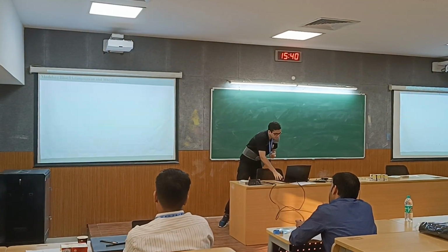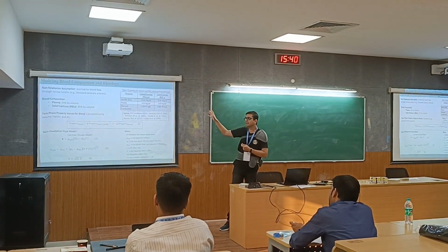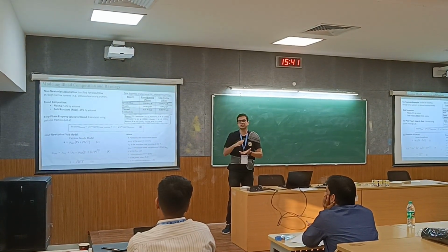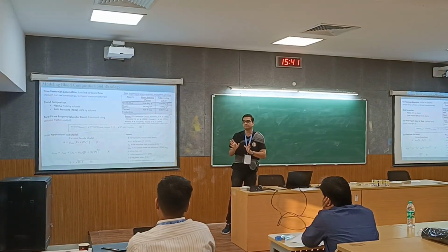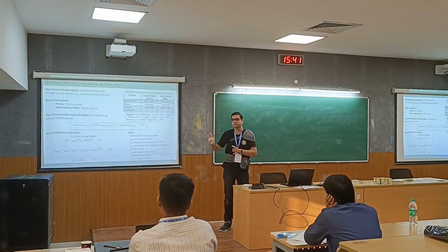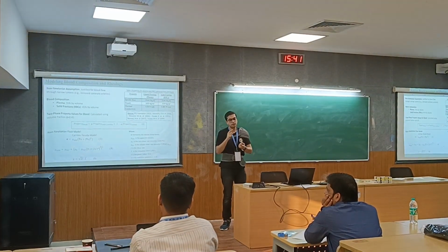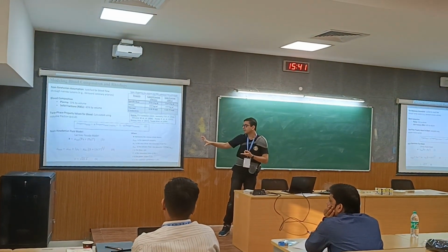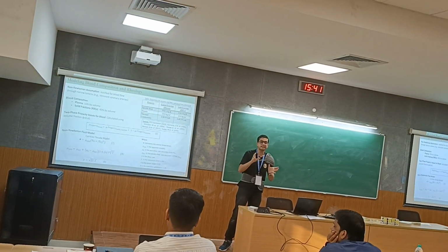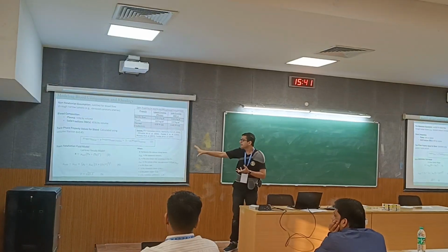Thereby, when we started modeling the blood, this is one important parameter: how do we model this blood? If you see most of these computational studies, they simply assume blood to be a Newtonian fluid so as to make calculation simple. What we did was incorporate non-Newtonian behavior. There are several models for that, but the one which is more suited for blood rheology modeling is the Carreau model, because we know that blood exhibits Newtonian behavior at very low shear rates and at very high shear rates. In between, it's a pseudoplastic thixotropic behavior that we see. So thereby we use this.